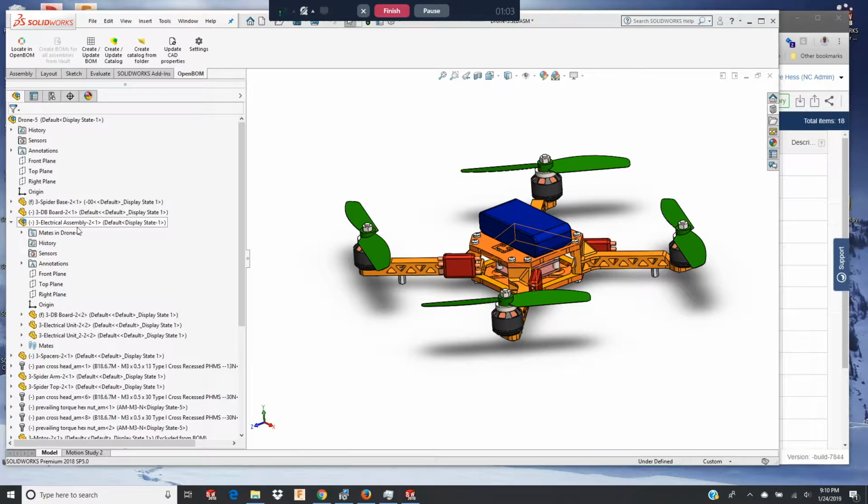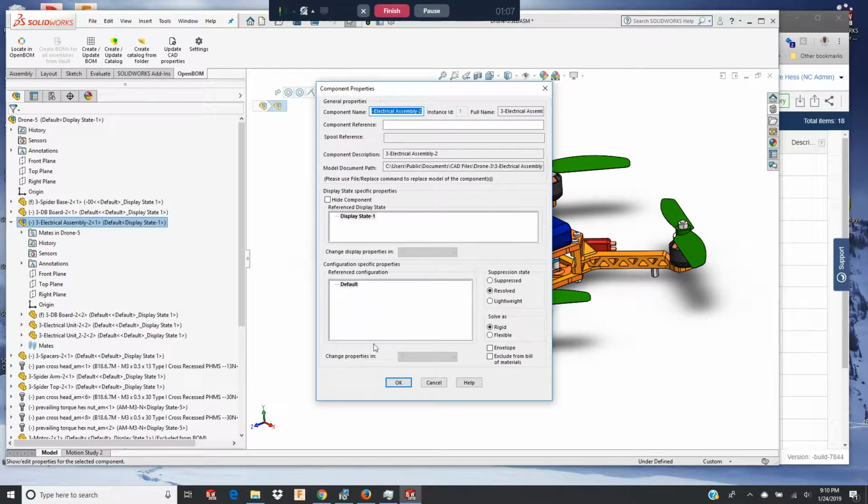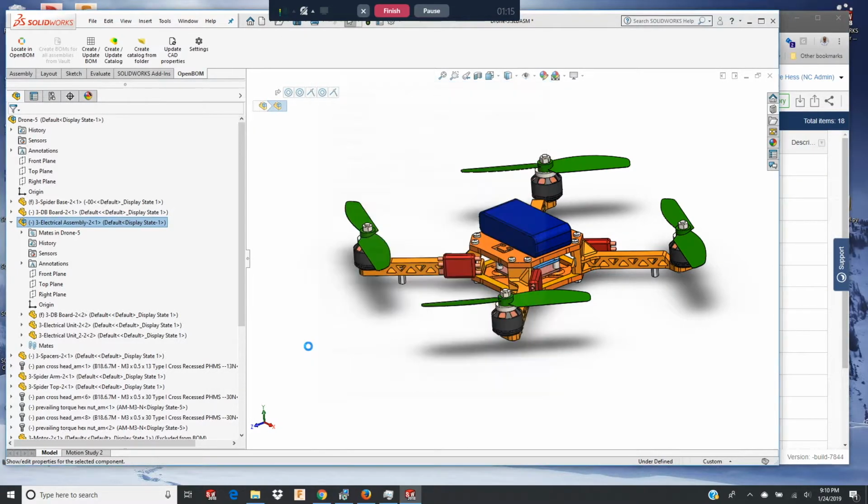So in this release, what we are doing in the SolidWorks integration is we are going to respect the envelope switch. So in the assembly's custom properties, let's enable envelope and we'll see the little envelope icon show up there. And what that will say to OpenBOM is, hey, bring everything multi-level that might be in this BOM, but for this particular item, only bring the top level item. Still call it an assembly, but we'll treat it as a part.